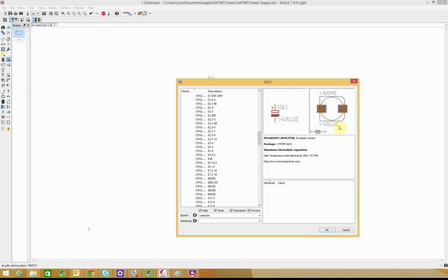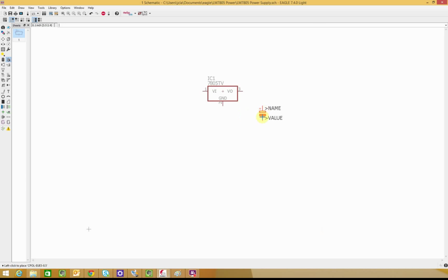It's only the footprint that differs. But nevertheless, you want to choose the right footprint, otherwise your PCB will be wrong in terms of how you want to mount your components. So here you can see the diameter of the capacitor. You want to keep an eye on this because that tells you a bit about the pitch between the pins. So in this case, we'll just select this one, press OK, and we will add these two capacitors to our schematic design, like this.